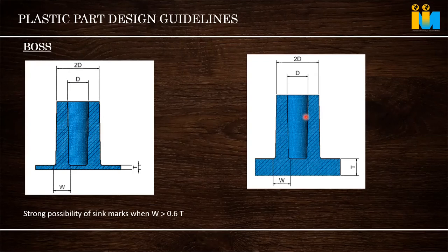And for threading applications, always go for a crystalline plastic, not an amorphous one. Don't give a self-tapping thread in polycarbonate or polyester, it cracks. That's why whenever we see a thread, it will be a semi-crystalline material in most cases. Otherwise, you have to over-design that product. Just to provide a thread in an amorphous material, we have to increase the thickness a lot, because amorphous materials crack. Internal molded-in stress is more for amorphous.